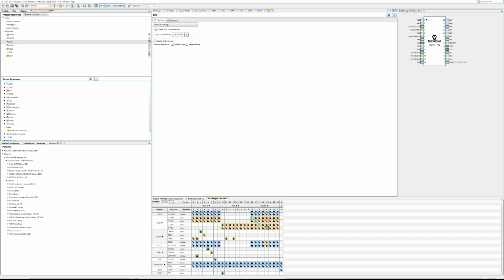the pin logic threshold voltage, which is usually around 2 volts. So if you're looking at, say, 12 volts AC, and you have your pin logic threshold of 2 volts, you'll find that the positive going part of the AC wave, you'll have a zero crossing sort of closer together for the positive going part, and then it'll be further apart for the negative going part, because you've got that 2 volt offset in what you're counting as zero crossing.